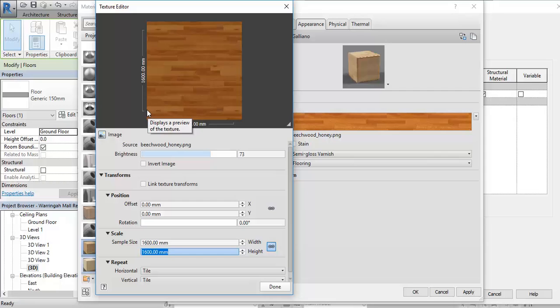Again, if it's bricks, you can just work out the size of a brick and multiply that by the number of bricks you see in your image. So again, think in real world sizes, and you should be able to work out the size for all your materials. Bit of a trick though is to oversize them. Sometimes people even make things double or triple the size of the material in the real world, just as a graphical effect, and that can work really well sometimes for the sorts of presentations you do. But at first maybe you can start off with the real world size.